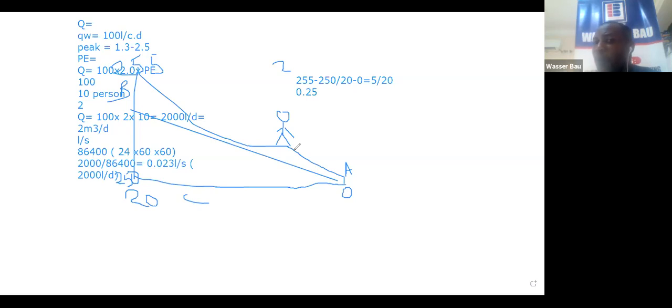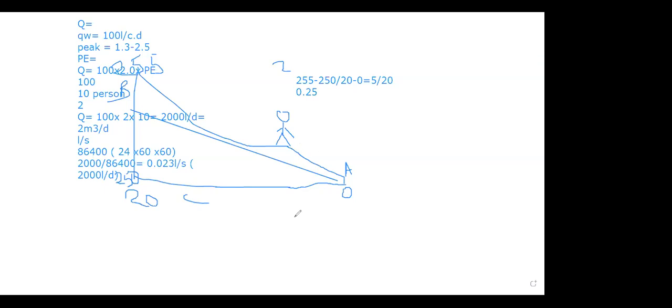The overburden must not be more than 1.2 so that the pipe will not break or suffer any structural defects. So for the bigger diameter pipes, definitely you have to go as deep such that the overburden will be adequate to provide some level of protection. I don't know if that answers your question, sir. Yeah, thank you very much.